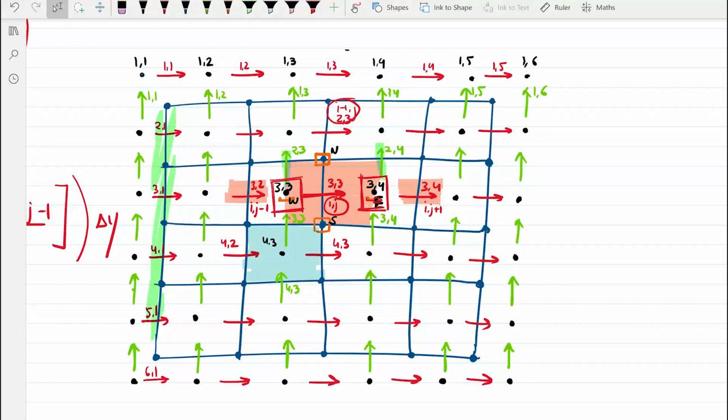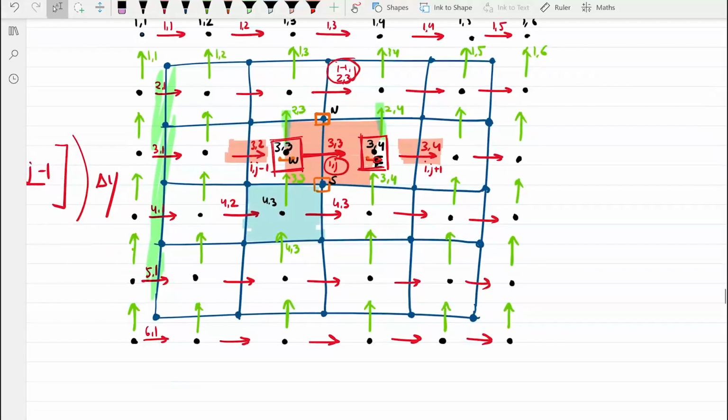In the y direction, there are changes, there is a boundary layer that develops, and there are no slip boundary conditions on the top and the bottom wall. So we would be using a periodic boundary condition in x, whereas the no slip boundary conditions in the y direction. To implement the periodic boundary condition, the idea is very simple.